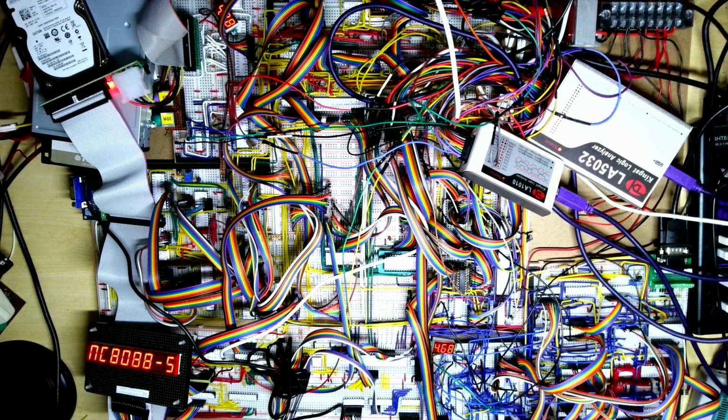Now this monstrosity over on the right hand side here, this is the full CGA IBM PC compatible video controller. So this is completely compatible through the memory map and through the registers. It does actually produce the VGA output so that it can hook into all the various video capture devices I've got. So it isn't actually producing CGA output, but it's not that easy to actually integrate CGA output into video capture. I've also used this with external monitors as well, which obviously I don't have a CGA monitor, so that's not an option.